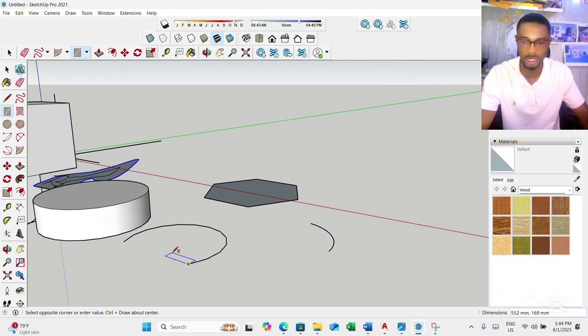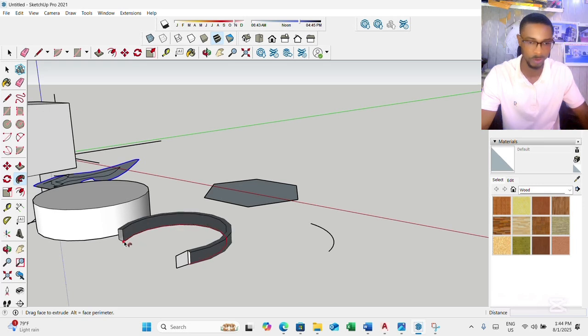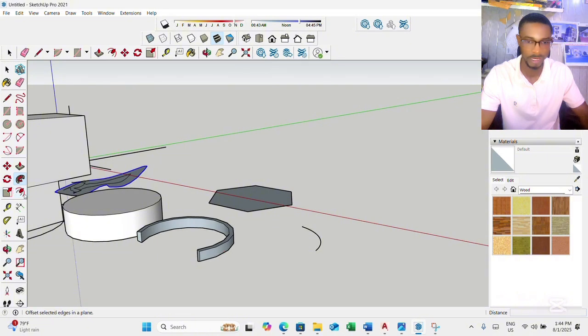This is push or pull. You click on push or pull. You pull it up. You want to pull it in, out, push or pull, any style. This is push or pull. And this is also rotate, just to rotate something. So you want to rotate this circle, one side, you rotate it. If you want to rotate this one here, then I will rotate it. Understand? Anyhow you want to rotate it, you can do it.